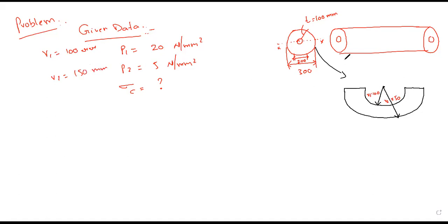So what question did they ask you? The first thing, he is asking you to calculate the maximum circumferential stress. Along with that, the variation of hoop stress and radial stress across the thickness. How does it vary in this thickness? I told you one point yesterday. What is that point, the star mark? In any thick cylinder, internal stresses will be maximum or minimum?